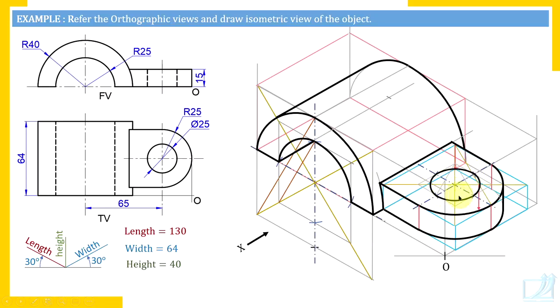It's just a possibility. So how to check it? Try to understand. An identical isocircle is at the bottom here. So visualize that. Don't draw immediately. And you will realize that only that longer arc portion here will be visible, if at all it is visible. This longer arc, where is its center? That is the end of the shorter diagonal.